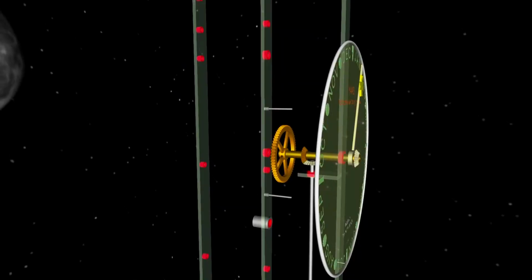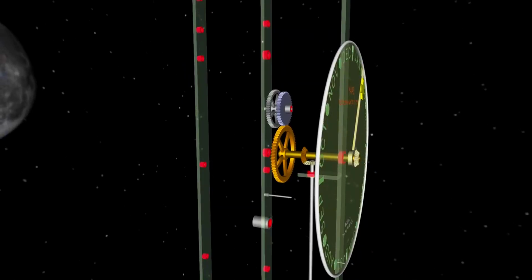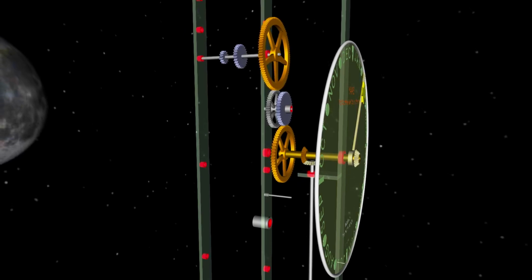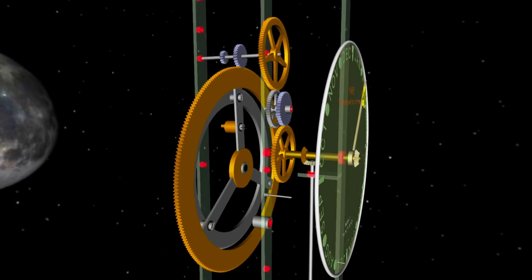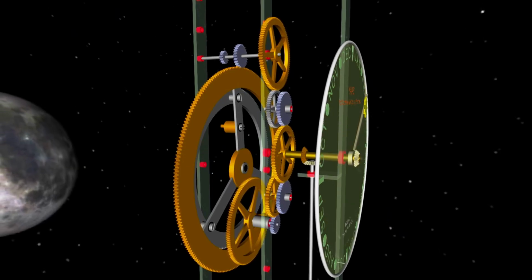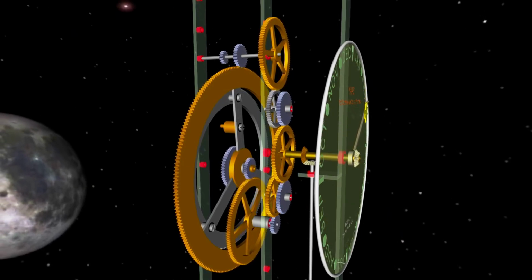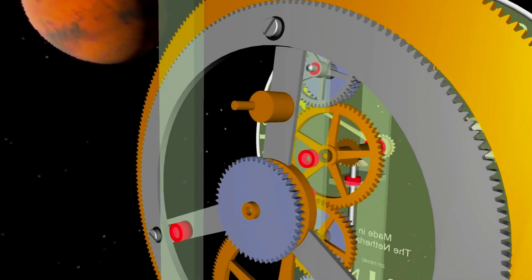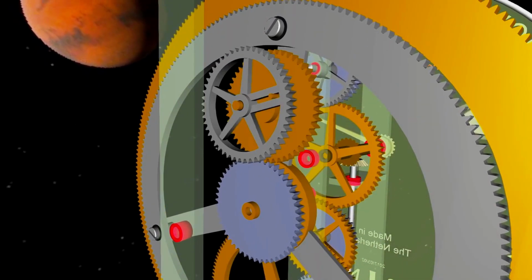This gear type is used to transfer mechanical motion and power between parallel shafts, allowing for the control of speed, torque, and positioning. This transfer can be made by a compound train, where multiple sets of gears are arranged to transfer torque and rotational speed from one to another until the desired values are achieved.